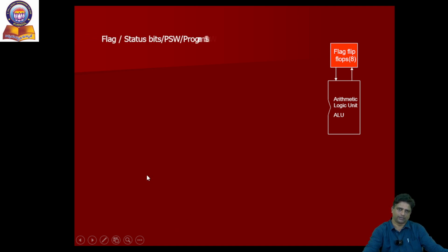In the same way, we will have another prominent register, the control register, an 8-bit status register for the 8085 microprocessor. Out of this 8-bit arrangement, 5 prominent positions are indicated with respect to the 8085 design. They are CY, carry, parity, auxiliary carry, zero and sign. The positions of these are very important to be represented.